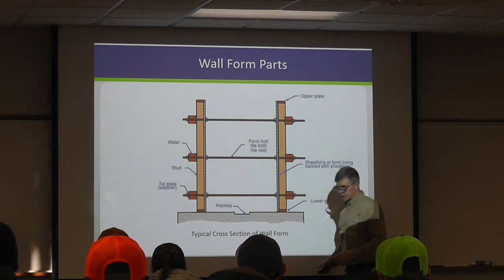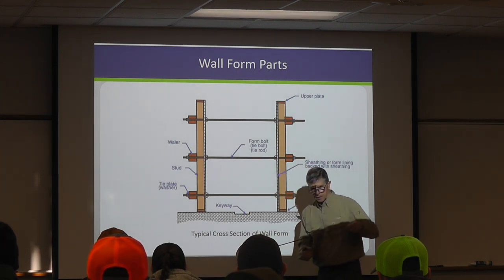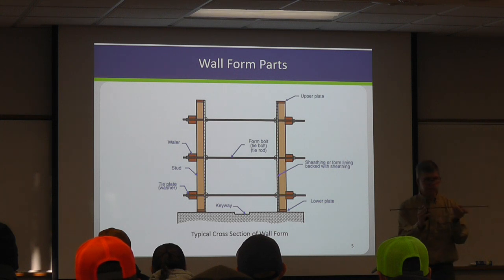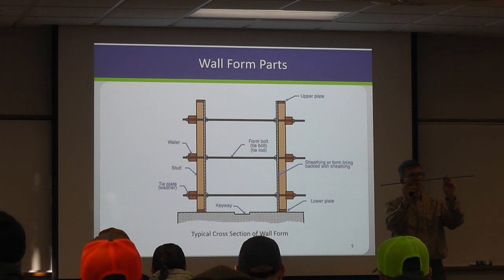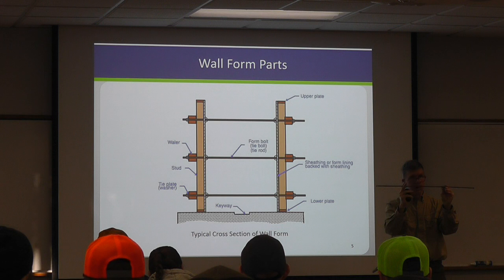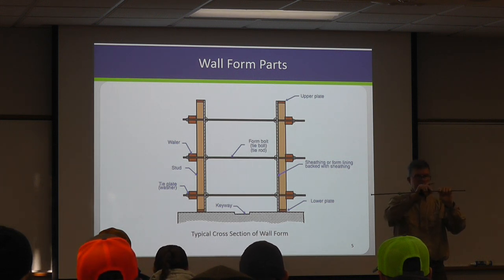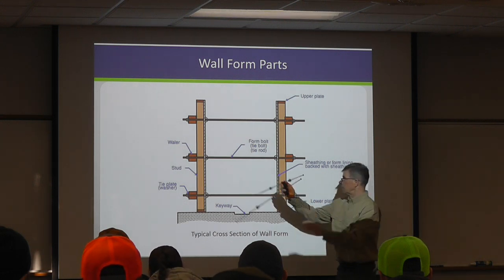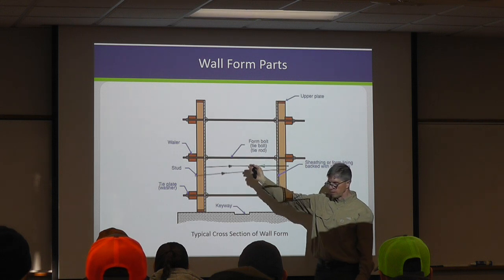And so we have a few samples of things. So this is, for instance, something that would be used to tie a couple of forms together. So the wall forms would be here. These little cones, we'll talk about that in a bit. After you break off, these things have a weakened plane, and so they can break them off once the concrete is cured. And you'd be left then with a little cone that you fill up. But that's similar to what's going on right there.